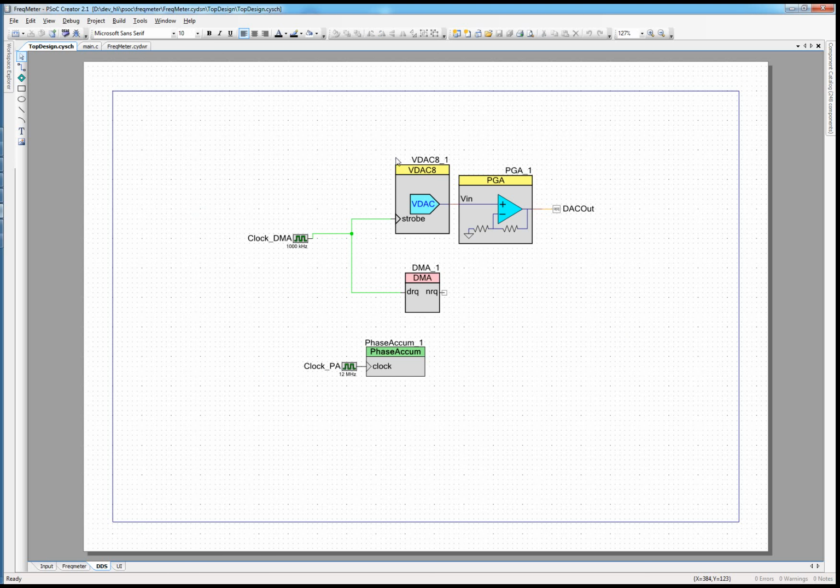The other way for creating waveforms uses what is known as a numerically controlled oscillator. It, at its core, consists of what is called a phase accumulator, which is nothing more than a counter, which is not working as a normal frequency divider, but it just adds a predefined step value to its counter and uses part of the current counting result as the lookup pointer into the waveform table.